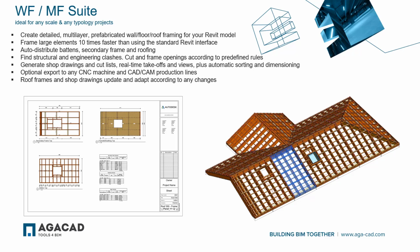You can auto-distribute structural framing elements, produce shop drawings, and number elements in the project to get accurate schedules when the time comes. You can also export to CNC, IFC, NWC and various other formats, and the model can be shared with consultants or sent for manufacturing.